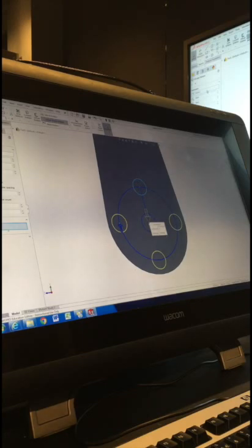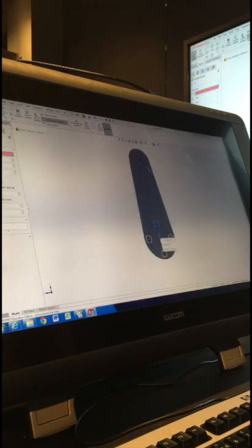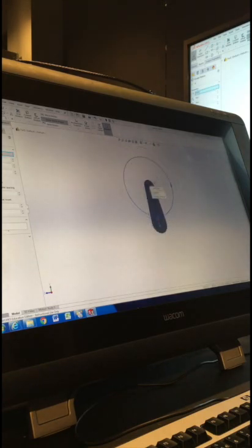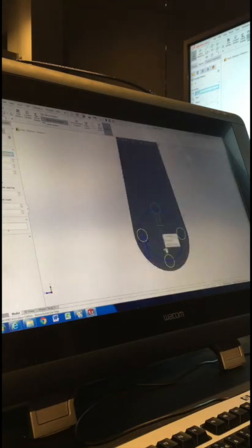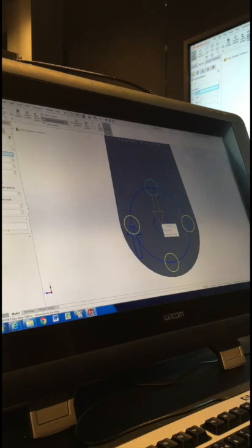If we wanted to pattern around a different point, we just click up the top here where it says axis, okay, in this very top box, and you can manually select any sort of point to pattern around. All right, so you can vary that. It doesn't have to be the origin. The next box down, we've already got equal spacing ticked, I think, by default. Change the number to 6, and you see how the pattern increases.